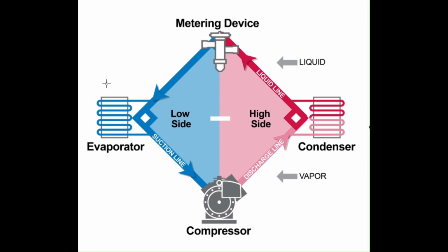Conversely, if we feed too much liquid into the evaporator, we won't consume all the liquid inside the evaporator, and we will end up with liquid coming out of the outlet and going to the compressor, which can cause mechanical damage, liquid slugging, and other undesirable effects.